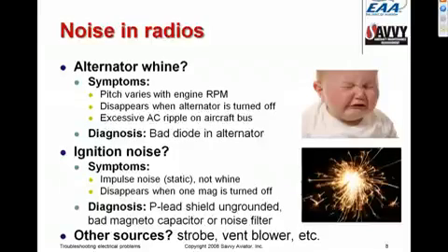If you have ignition noise in the radios, the most common cause is that the P lead, which is the wire that goes from your ignition switch in the cockpit to the terminal on the magneto and is used to ground out the mag when you want to turn it off, that P lead, which is a shielded wire, has had its shield ungrounded.